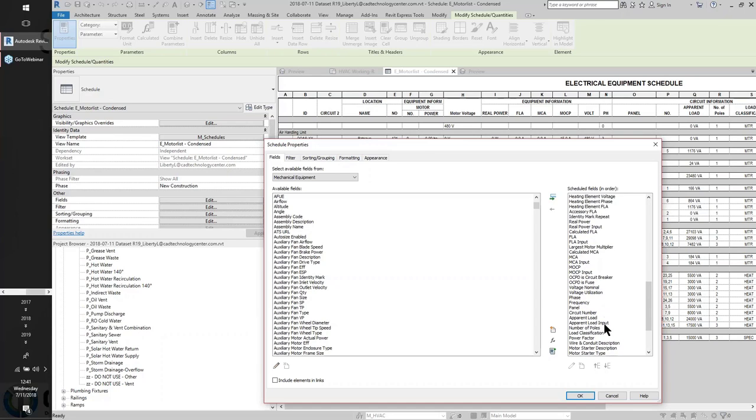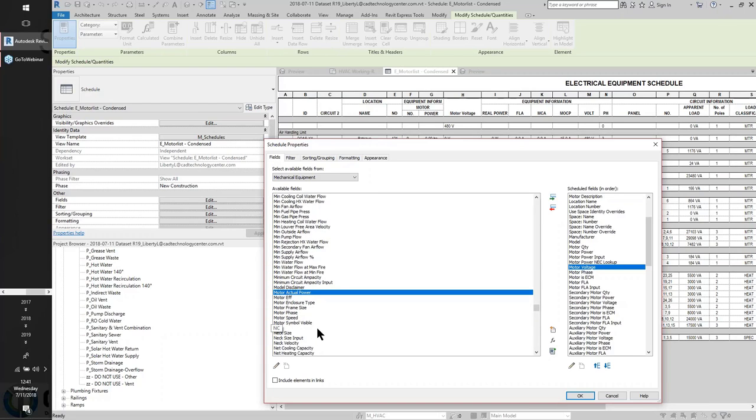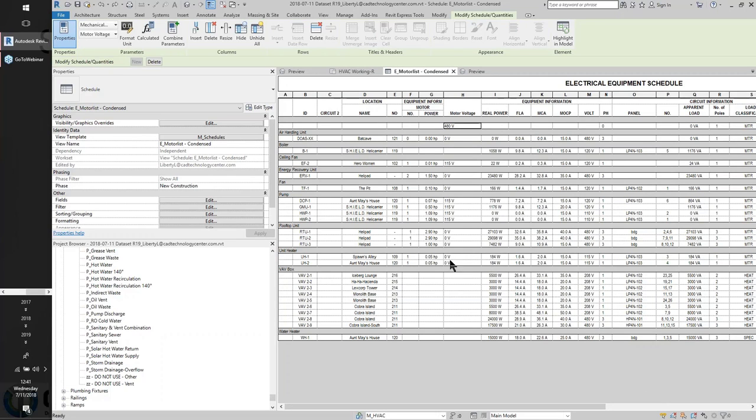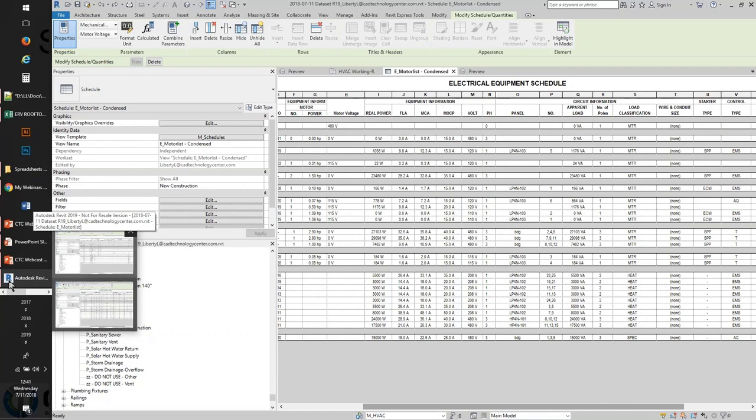The only way we can check is to see the GUID, but for right now, it looks like we do have the correct one. But if we have another one that exists here, that means we do have duplicate parameters. So it's just one thing to think about and troubleshoot in case you run into this issue. If in doubt, after pushing the changes from Spreadsheet Link, you are not seeing anything populate, just check your fields and ensure that you've got one set of parameters, especially on the calculating / analytical side.